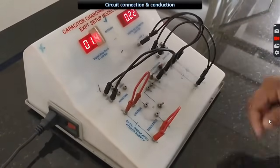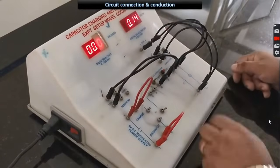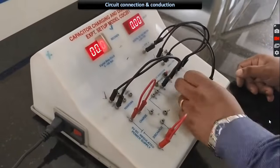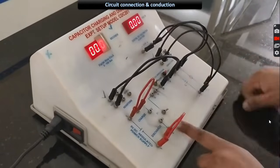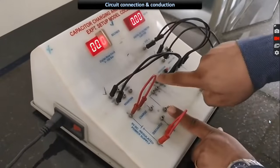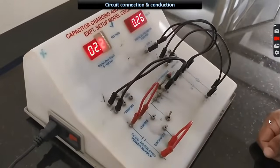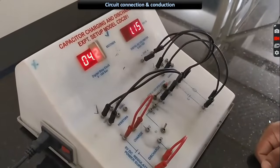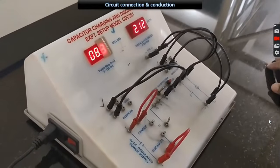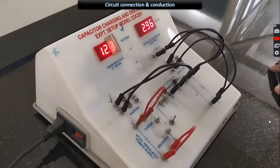Suppose the stop clock is not 0, reset it. And suppose the capacitor is not 0, you have to discharge the charges abruptly. To do that, take out one end of the capacitor and touch it to the other end. While you start the experiment, keep the knob in the discharging position and press the charging and start button simultaneously. And start taking readings for every 5 seconds.